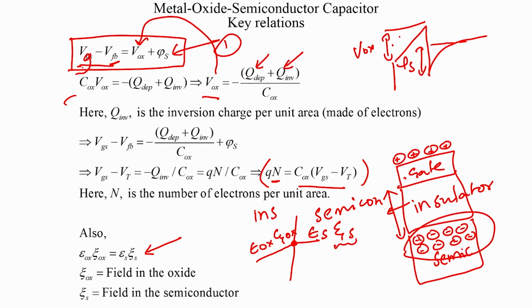And you can calculate the electric field in the semiconductor by solving Poisson's equation, and that calculation will have an xd or a phi s dependence on it, and by using this relation you can estimate what phi s is. And what is the electric field in the oxide? It is simply going to be your Vg minus phi s by T ox in a very crude sense, if there are no trap charges in the oxide, etc. So, therefore, you have two relations with phi s in it and you solve for phi s, and these are not easy equations to solve.